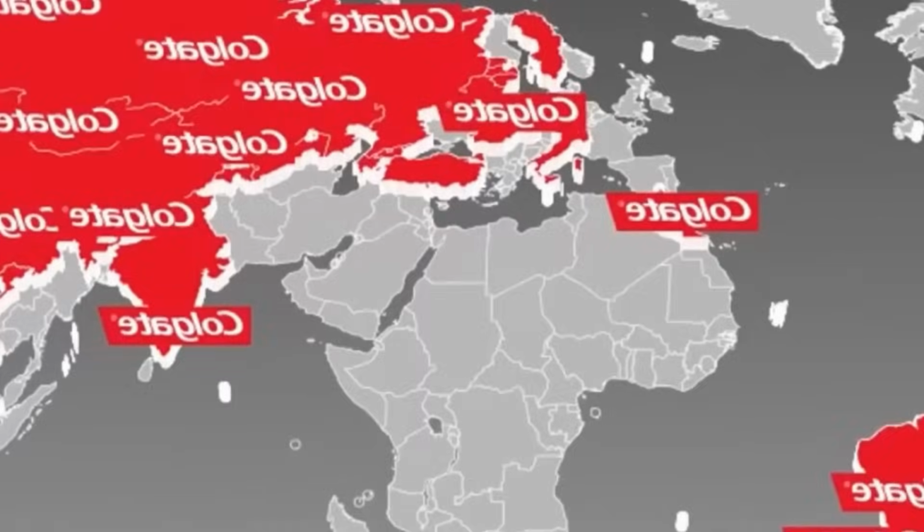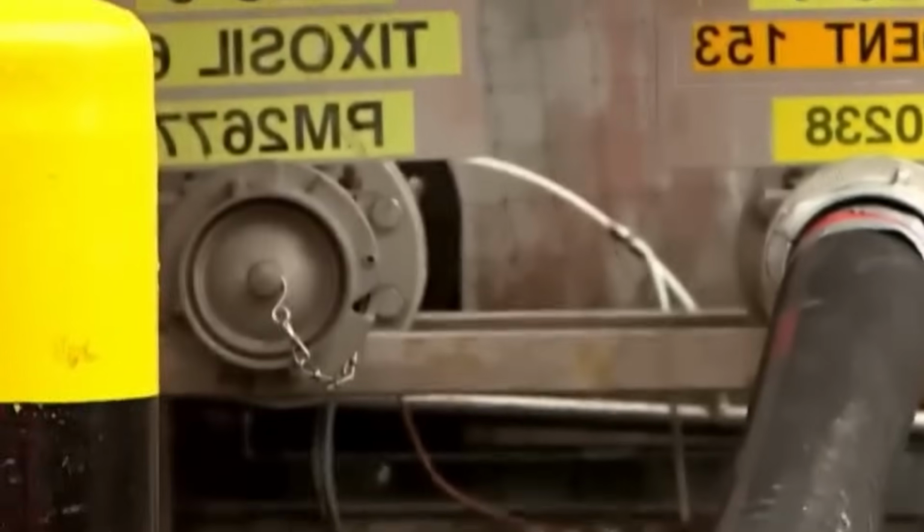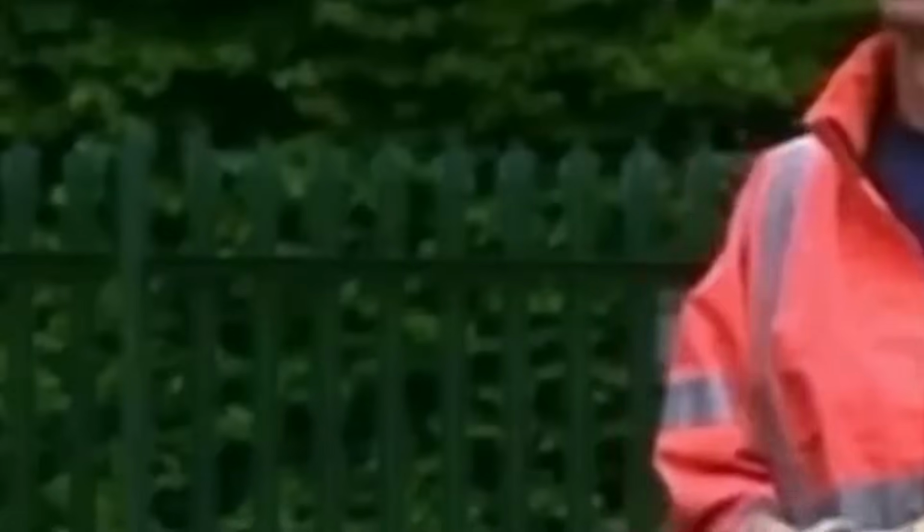Deionized water is introduced in precise volume, based on formulation requirements. The water is pre-treated via reverse osmosis filtration and UV sterilization, then dosed into the batch using mass flow controllers to ensure accurate hydration of solids.